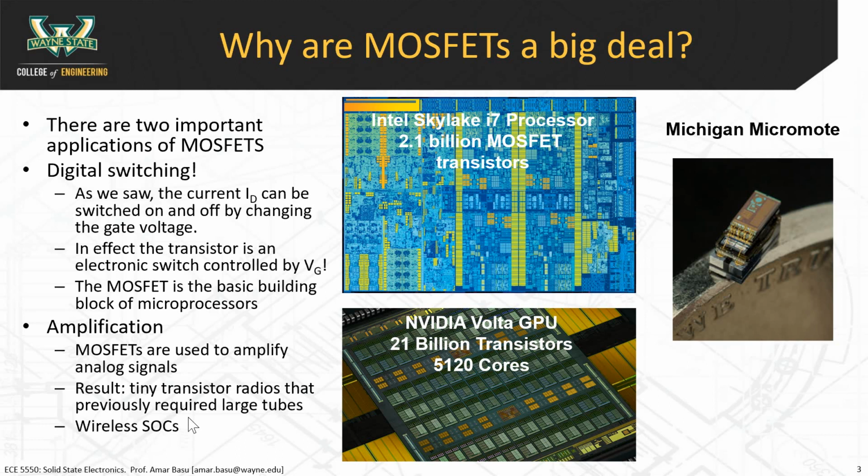But making a bipolar junction transistor required a different process entirely, whereas all the computational stuff, all the CPUs, were being made in a CMOS process. The bipolar junction transistors had to be made in a separate bipolar process. So you'd have separate wireless radio chips made in a different process and separate microprocessor chips made in the CMOS process.